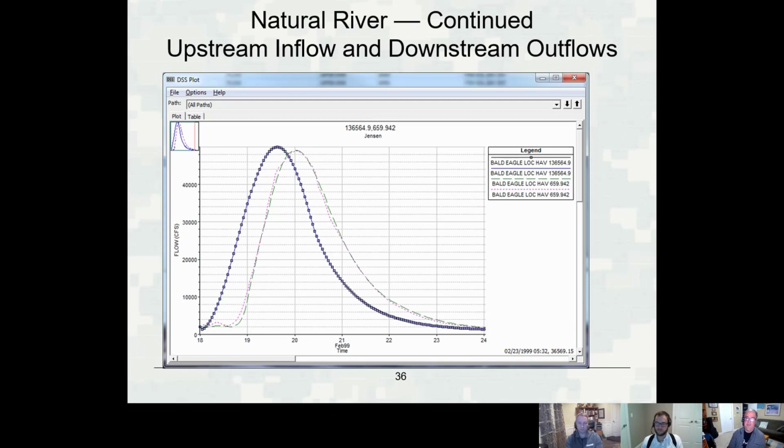Okay. And we did that on purpose so the results would be more similar to the current model. But future versions are going to have an option that you can compute the volume based on the terrain, like it does for 2D. Right now the volume is really an average of the end areas, which is similar to the 1D approach. The volume between cross sections is an average of the areas. If we didn't do it that way, the results would be vastly different. So I wanted to do that first on purpose.